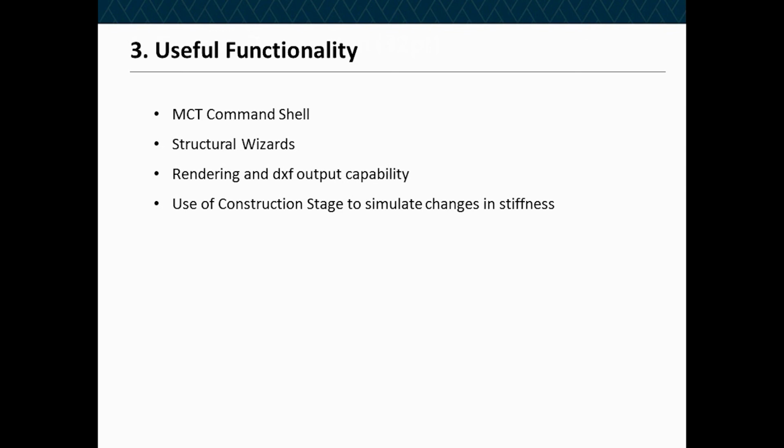So we would force the displacement of the structure and at the same time have an E value that varied with time so that we could simulate the variation in the material for that structure. So you can use the construction stage analysis tool quite differently and innovatively to do things that are otherwise, frankly, not commonly possible. I'm sure that there are many other things.